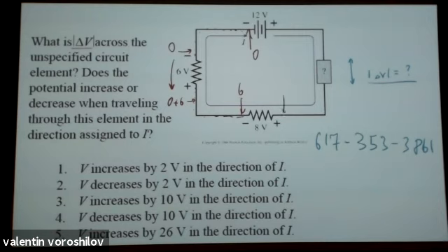And now here we should have potential higher by 8, and 8 plus 6, 14 volts is the potential on this end. And now we go to another part, and the potential here is relative to 0 equals 12 volts. 12, 12, 12, still 12. So the voltage, which is 12 minus 14, magnitude 2 volts.